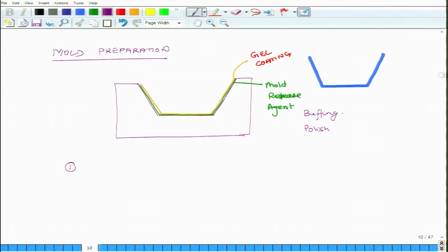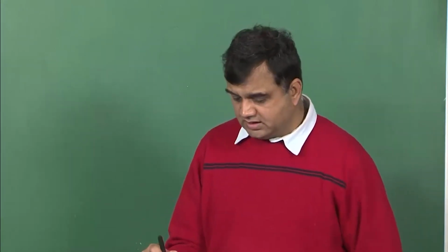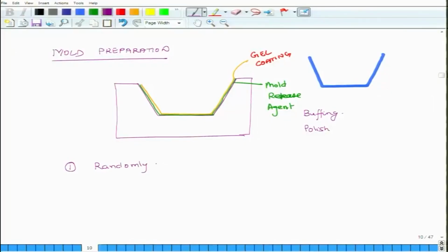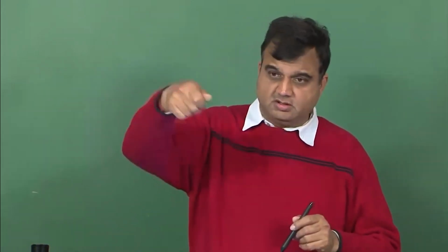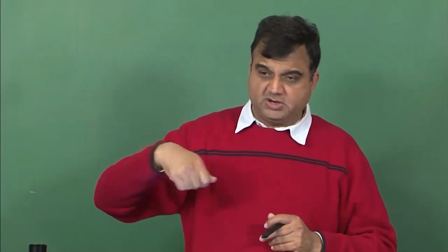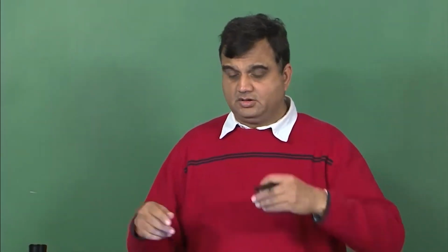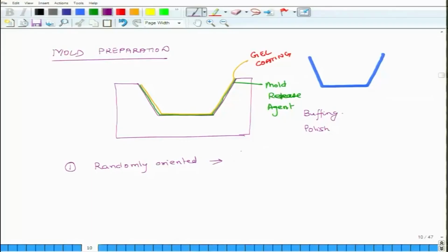Okay. So, if the fibers are randomly oriented, then what you do is you have small length of fibers, and through some nozzle you spray them, and because you are spraying them they fall in all sorts of orientations, and you keep on spraying it on top of the mold, and while you are spraying it on top of the mold, through another nozzle you also spray matrix in fluid state simultaneously. So here fibers and matrix are sprayed,